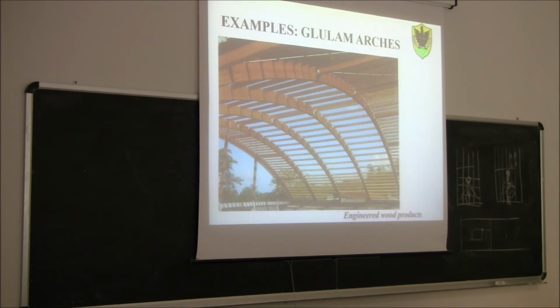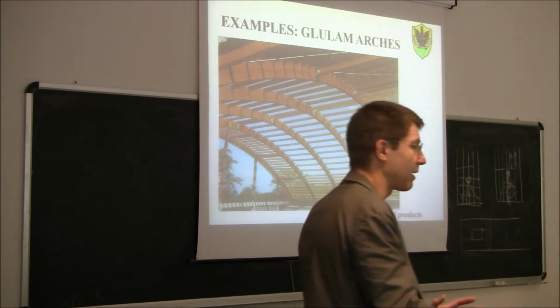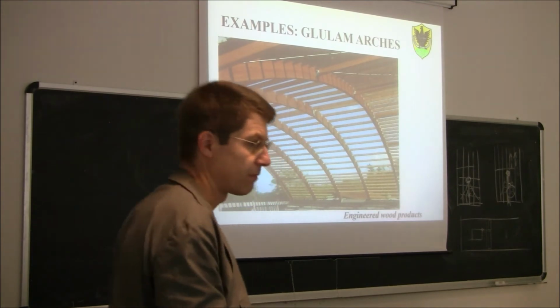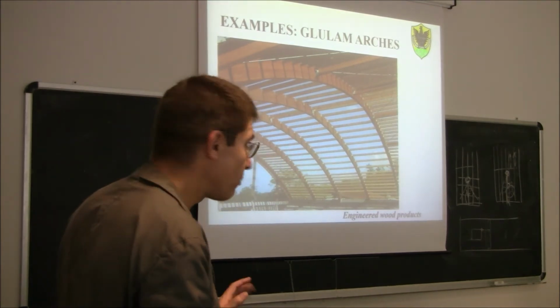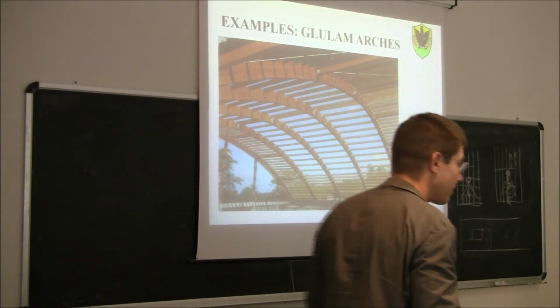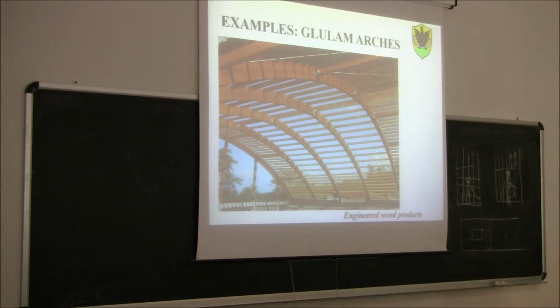And we will see when we do a calculation of a timber beam that without these restraints, there would be no way to get the lateral torsional buckling verification satisfied. Okay? So this bracing system here is really needed for timber but also for steel construction to provide some lateral restraint to the arches, to the main frame. In this case, the 3 big arches are the main frame of the structure. Okay? So the first reason is this.